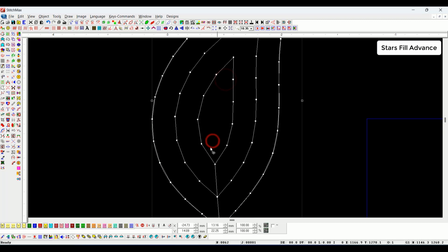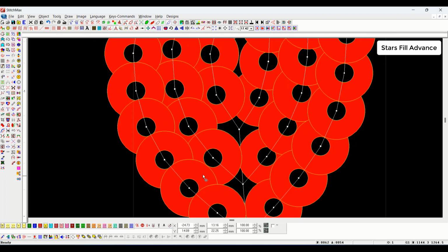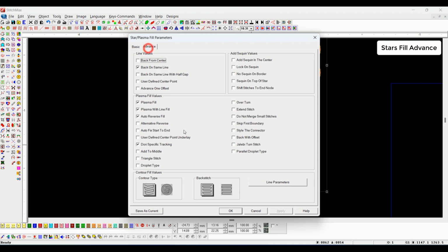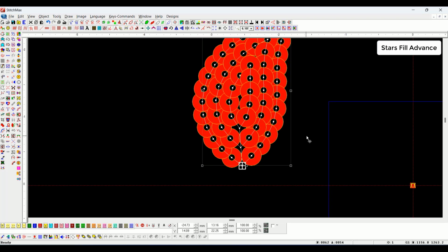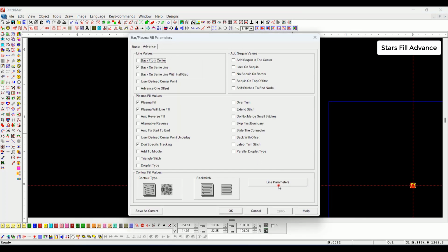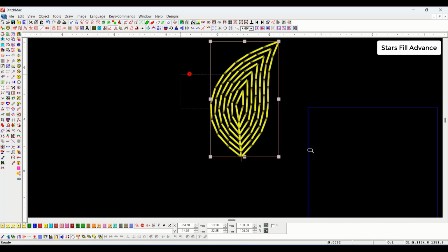If we want to add a sequin under it, then we can add it. To add a sequin, if you want to create an object with a sequin here, then the auto reverse fill that we had turned on for coding and chain will have to be turned off. So you can add a sequin from this way. Here we keep a stitch length of 3 mm, keep an offset of 0.8. We placed the same object everywhere here.